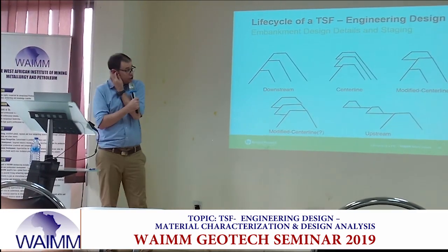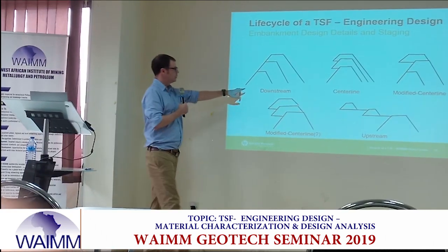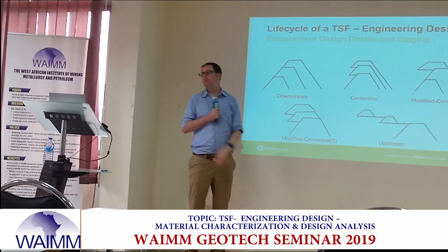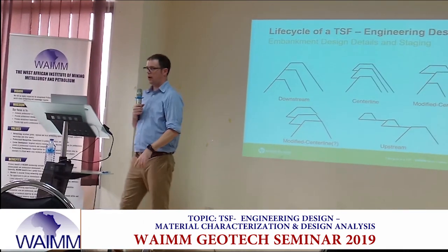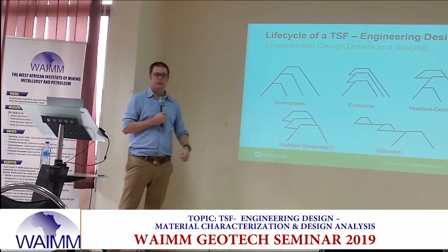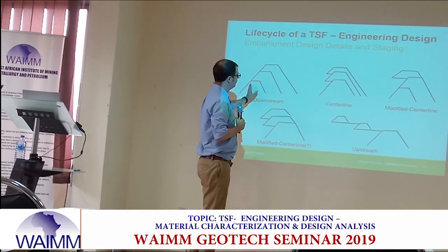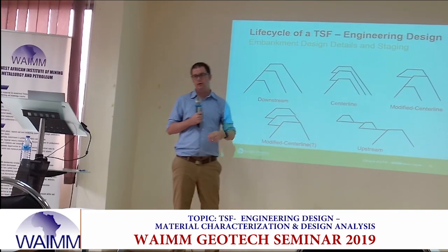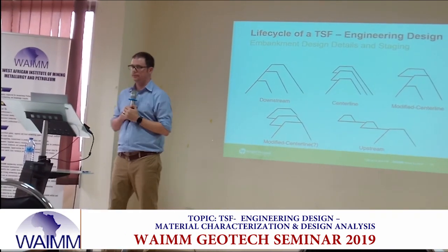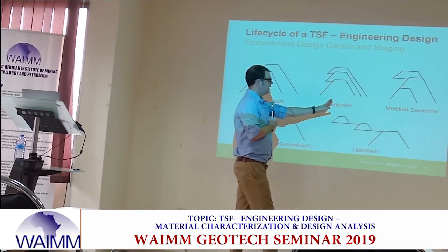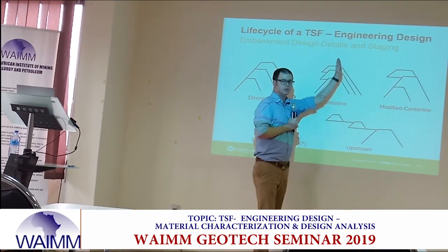The big issue that we have with these is what happens with the surface area here. It gets bigger every time, right? So that means the cost of each consecutive raise just goes up and up and up. Every stage you put on is more material, more cost, okay? This is what's called a centerline raise, where the center line of our dam just goes vertical.